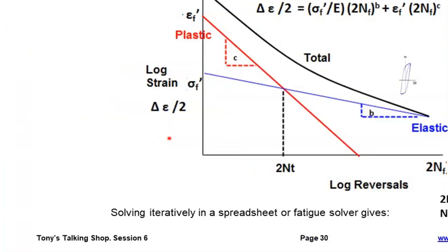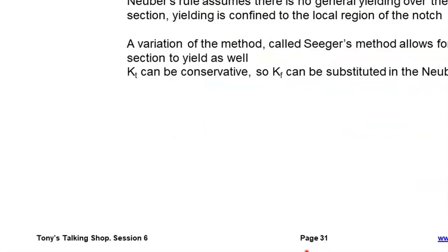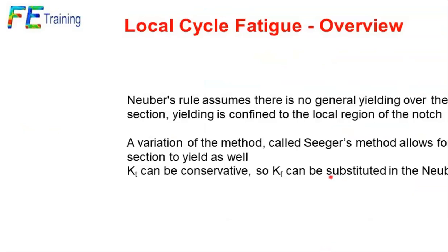I'd literally look at that peak, the linear stress calculation that's being used for the analysis, and see, are we close to yield? If we are, then I really want to see evidence that you've repeated that using a low cycle fatigue type of approach. So there are other extensions to that.